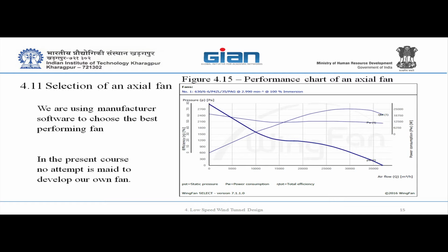It has to work against some pressure. One contribution is the jet power. It has to accelerate the flow from zero to test section speed. That's the main issue. You may calculate what the power of 80 meters per second in that cross section is. You just take that formula and find out what power is needed and what the pressure is. So that's the pressure you'll feel ahead of the fan.